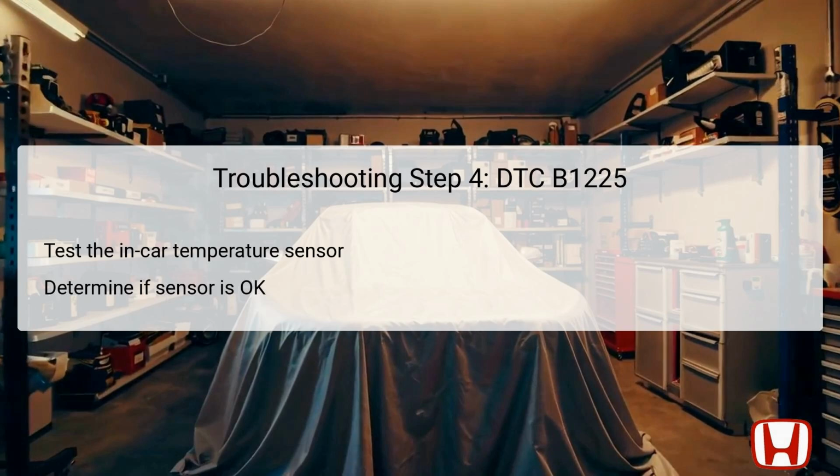Tests can involve measuring resistance and ensuring that the values fall within the specified range outlined in the vehicle's service manual. If the sensor is found to be in working order, it suggests that the issue may lie elsewhere in the circuit. However, if the sensor is defective, the technician would then proceed with replacing the in-car temperature sensor. Proper assessment ensures that all components related to the climate control system are accurately diagnosed, which is key in resolving